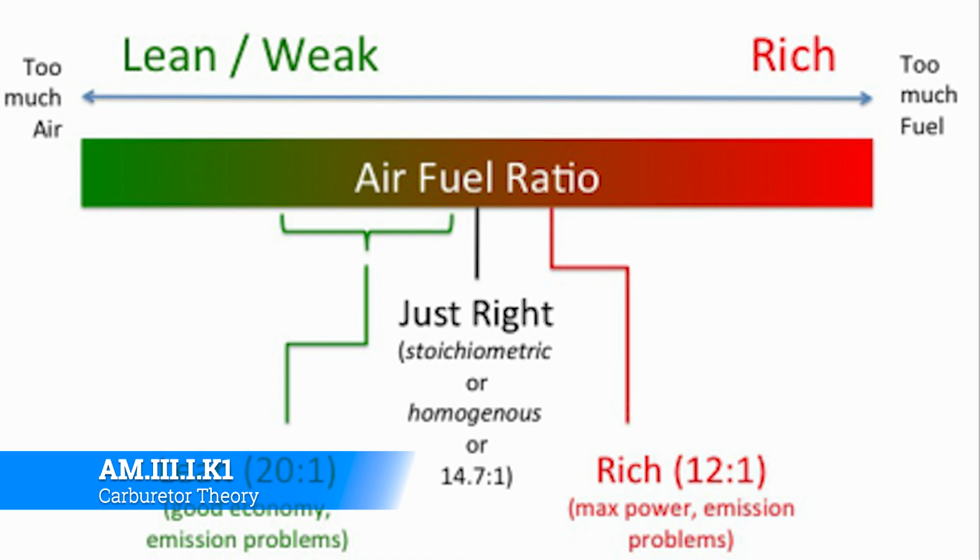air. So, if you have a piece of paper and you wad it all up and you go to burn it, it's going to go really slow because it's having to work its way through all those creases and folds. However, if you lay the same piece of paper flat and you light it, it's going to go really fast because it's a lot more efficient. All right. Well, atomization of fuel is simply the same thing. If you spray the fuel, those little bitty molecules in that atomized mist have 360 degrees around these very small bits of fuel, so that it interacts with the oxygen in the most efficient manner possible. So therefore, it'll fire off more reliably. Now, you could have a situation where, say, a cold engine.